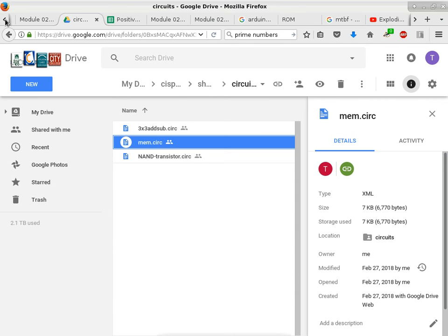But it also makes the data bus very interesting because the data port is not an output port anymore. Sometimes it's output, sometimes it's input. When you're writing to RAM, the D port becomes an input port. But when you are reading from RAM, the D port becomes an output port. So that is an interesting part of using RAM: the D port is bidirectional. It can go in either direction.